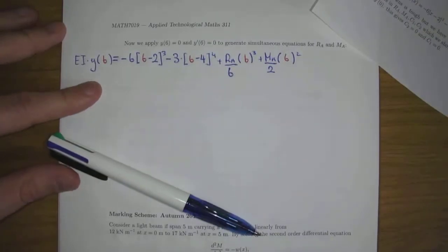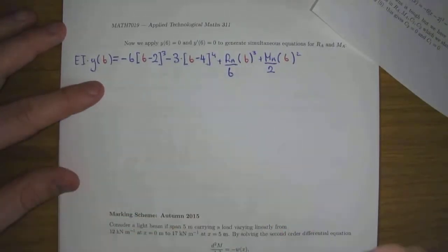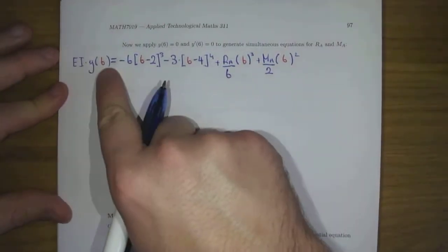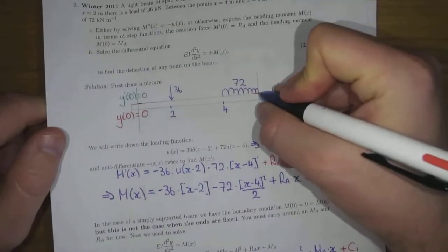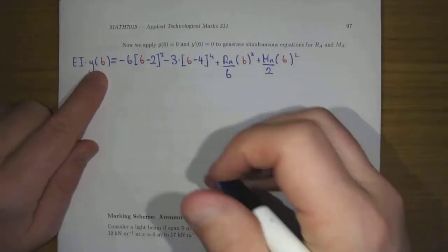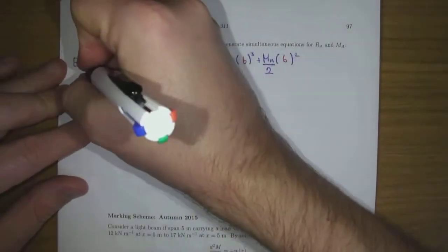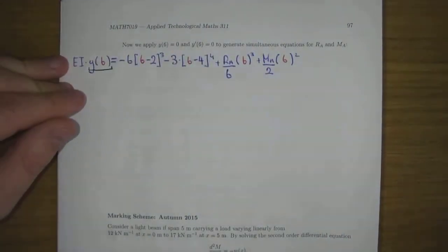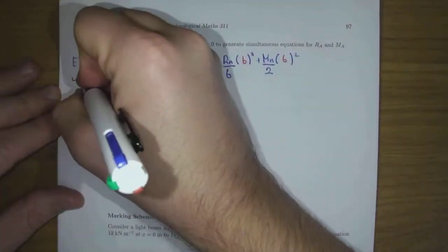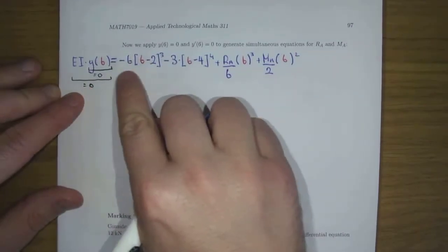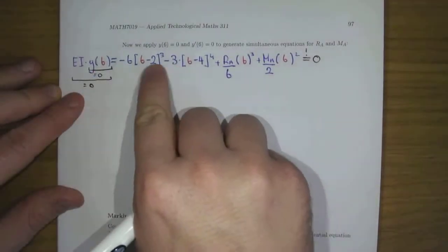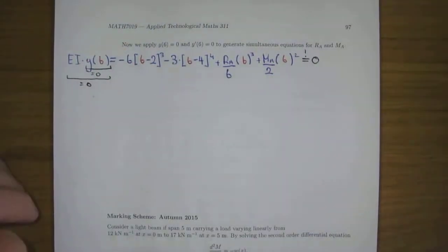So I've got the C1x and the C2, but as we said, they're 0, so there's no point dealing with those. So now what are we going to do here? Well, this is EI times y of 6, the deflection at 6, and there's no deflection at 6, the deflection all occurs strictly between 0 and 6. So this is EI times 0, which is something you want to understand. If you don't understand it, you're very liable to make a really stupid mistake. So this is 0, and EI times 0 is 0, so you don't have to write that, but when you write the equals 0 here, I want you to understand what you're doing. So this 0 is equal to this. I'm just putting the 0 over there, it's just easier.